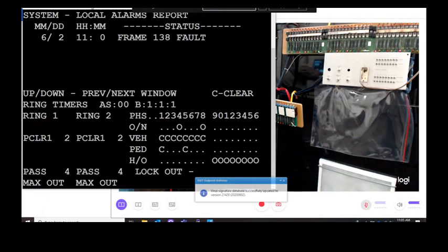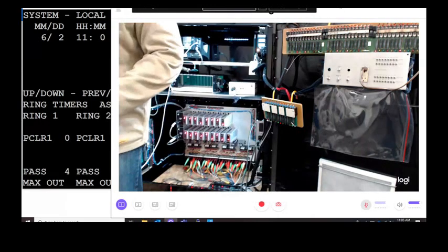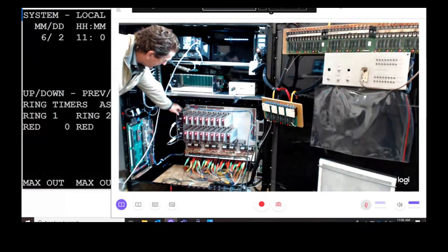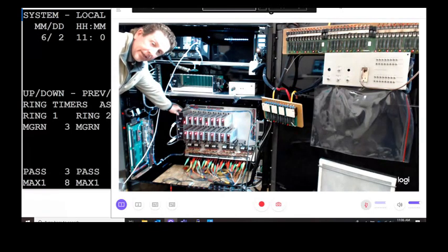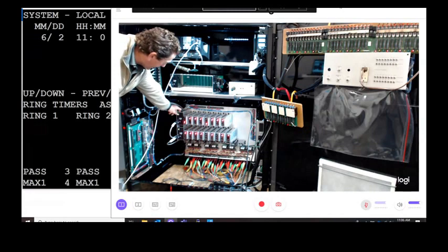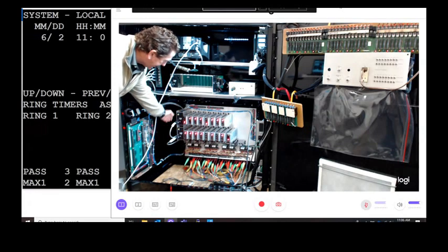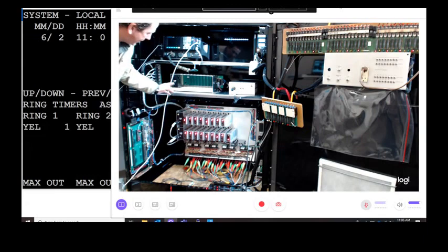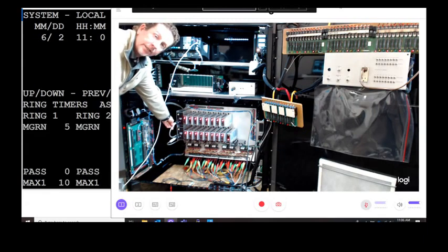If you got another BIU and plugged it in and it took off and ran, great, you're done. It's working. If you put another BIU in and it doesn't run, then I would try swapping the cable from here to here, or maybe the cable up here, because maybe the problem is in the cable.